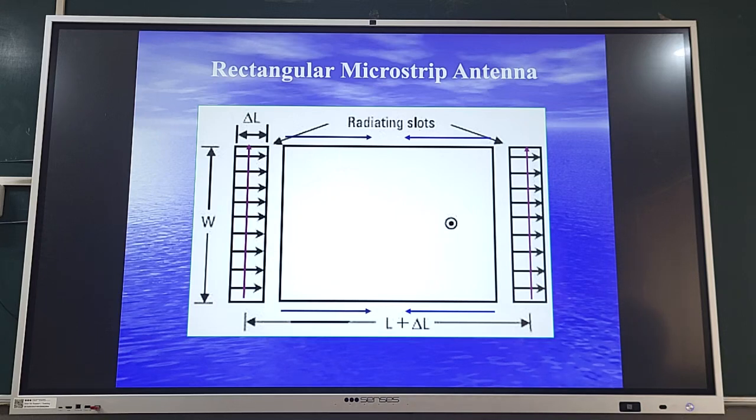As a layman, when you go to purchase an antenna, you are just interested in the horizontal and the vertical pattern of the antenna, or azimuthal and elevation, and that's what you will see in the data sheet of the antenna. But from the antenna engineer's point of view, that is not the way one looks at it. One has to go with respect to the principal planes of radiation, because that knowledge comes with respect to the resonant modes present. You cannot just define arbitrarily what is the E-plane and H-plane.